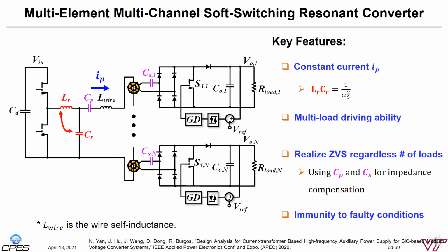The total power is over 120 watts in the design. It has a total of 6 channels and each channel can feed a 20 watt load. A 20 kV rated high voltage rubber insulated wire is adopted as the primary side winding to link all the transformers.